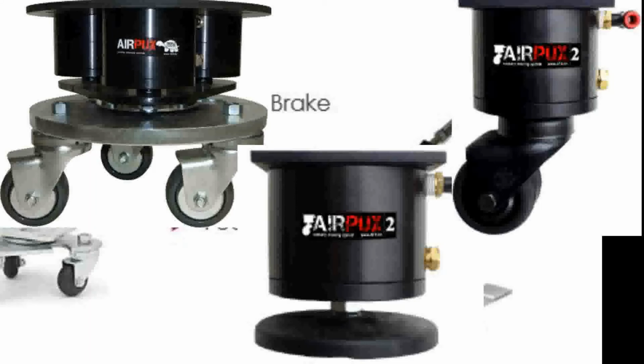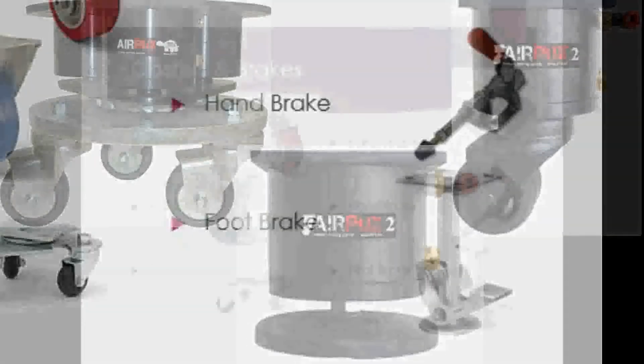But those are pneumatic casters, and you can use pneumatic brakes as well that act the same, but instead of the bladders pushing the casters down, what they would do is the casters would be set and you would be pushing a flat piece down to push the caster slightly off the floor and brake the platform. And then when you release the brakes, then the bladders get pushed down and the brake goes up.